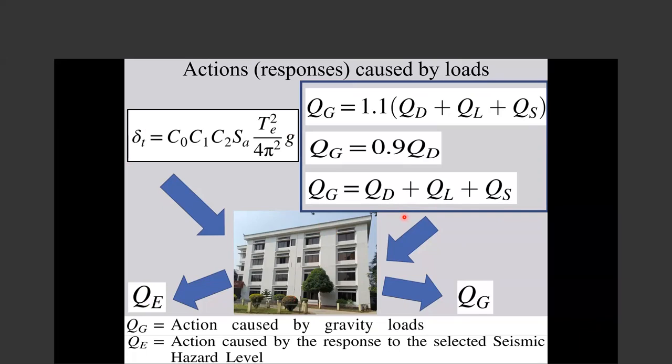But if the building reaches it, when you look at this, you should just see a set of force control and deformation control parameters, lots of force control and deformation control parameters in the beams and columns. You just see it. If one of the force control parameters reaches its lower bound strength, again we see that the building failed.